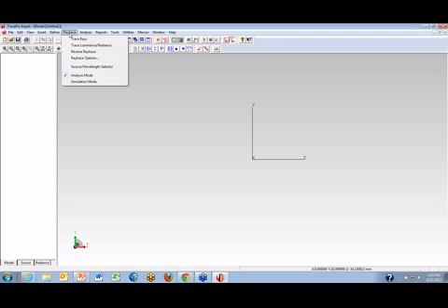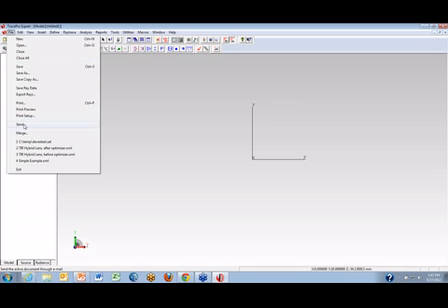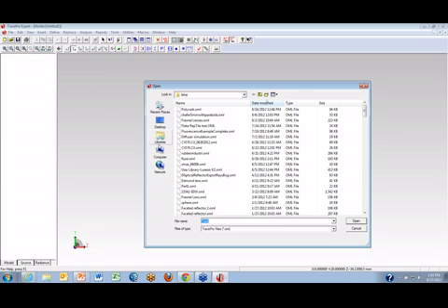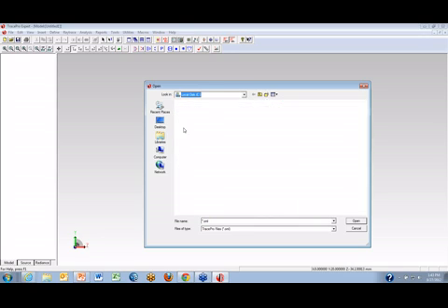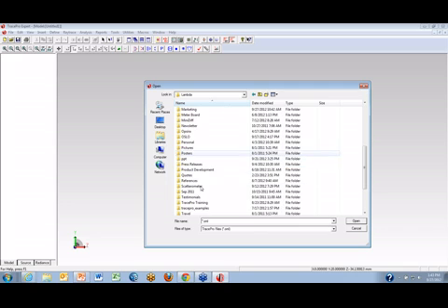I guess, Mike, while we're waiting for some questions here, one observation I always have when I'm talking about symmetry is that if you're going to apply symmetry, make sure that the system you're applying it to should have symmetry. I have seen people make mistakes when they've applied rotational symmetry on an object that isn't rotationally symmetric. So it's one thing to watch out for when you're using methods like symmetry and smoothing to reduce the numbers of rays that you have to trace.